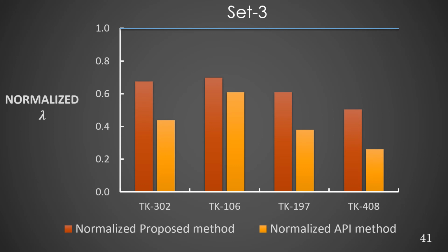In this figure, we have the results for normalized settlement amplitude for profile 3 for say 3 tank models. On the x-axis we have different tank models. On the y-axis we have normalized settlement amplitude. If the normalized settlement amplitude is greater than 1, it means that the method estimates a higher allowable settlement value compared to what we would get from finite element analysis. Therefore, the method is not good.